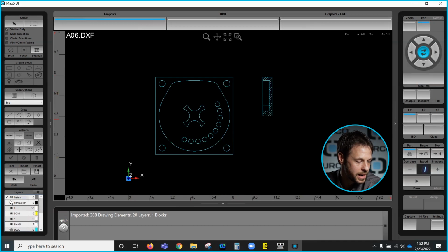Another icon that you may notice here is the icon that indicates which layer is active, or the layer that you're currently going to be adding geometry to or editing. I'm going to set that to the same layer that I have active just by selecting the box next to the layer. So now this is saying that that DWG layer is active, it's visible, and that is my active layer. Any edits will take place on that layer.